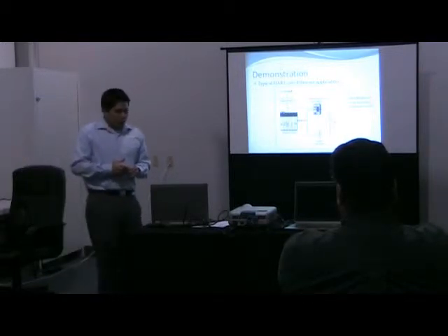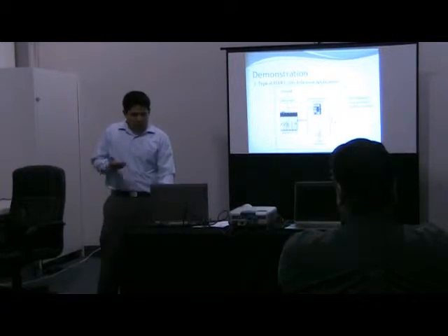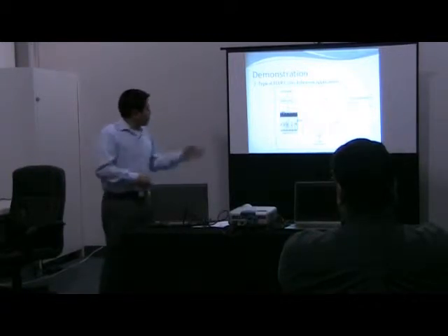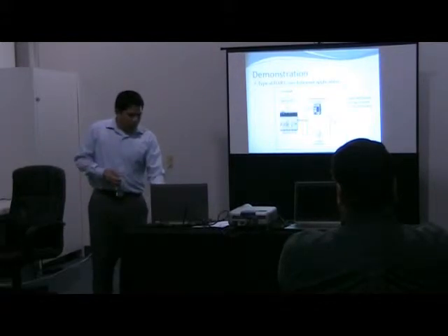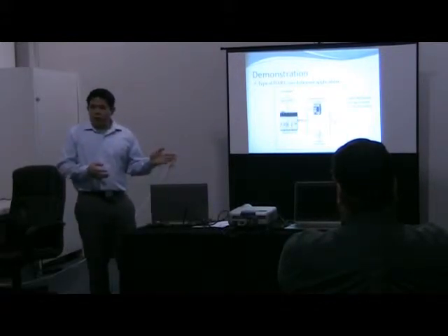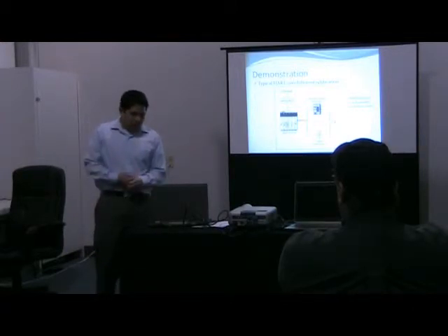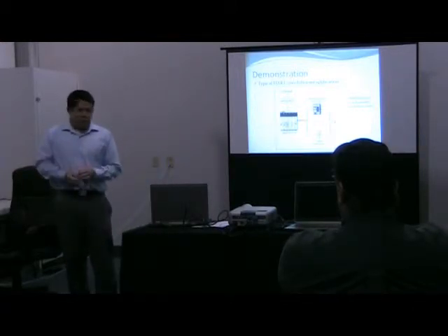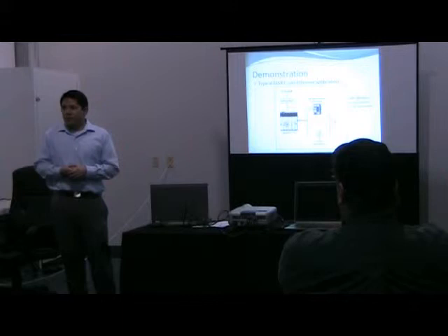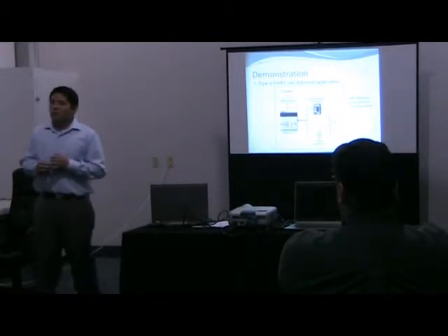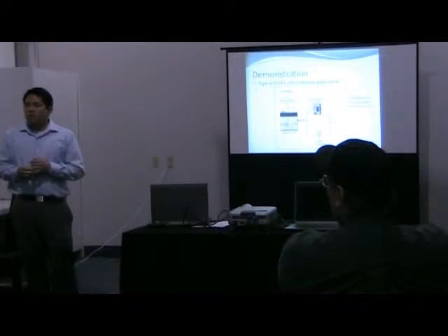Yes. If you look back at how we added the HART modem into the circuit, we had to break the connection first, so you wouldn't be able to install it on a running process. That's another concern. And like you were saying, Jeff, if something internally with the HART modem goes down, now somebody has to fix it. What we've experienced in the past is that with modems like that, you might have a compatibility issue with your analog input card.